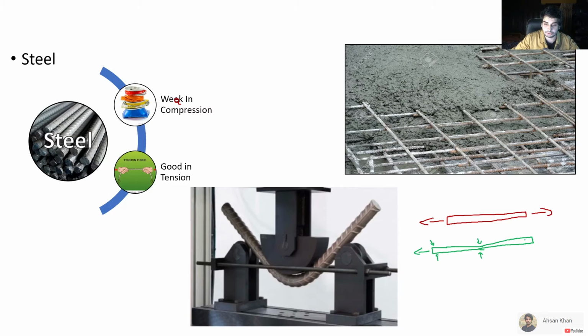And that's how the tension will be acting on it. And then there will be necking, which means it will become very thin. There will be a certain point that it will become very thin when you keep on applying the force, something like this. And after necking there will be a crack or fracture, and that steel rod will fail.